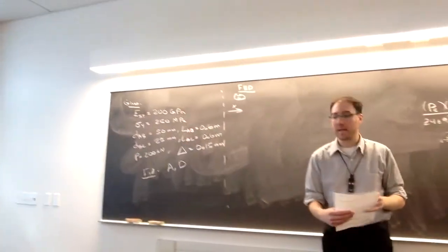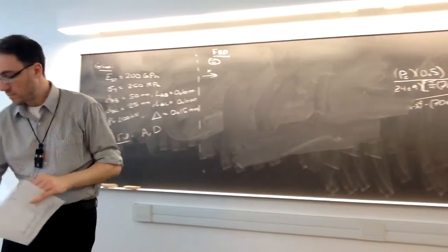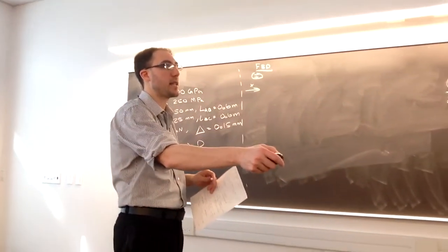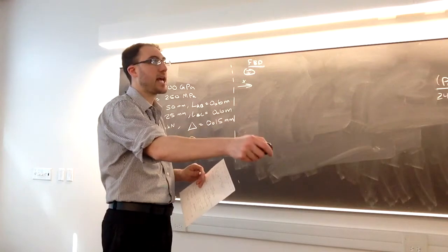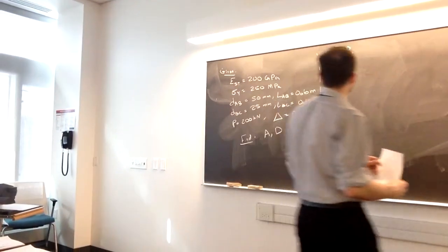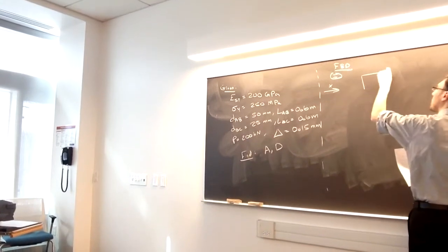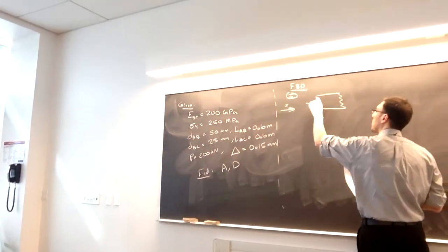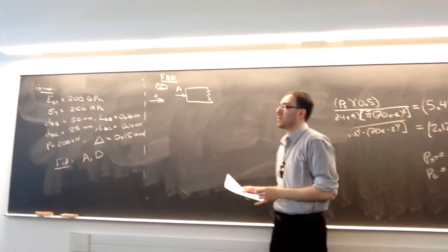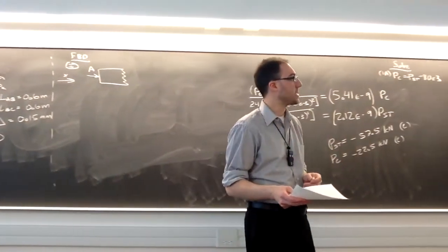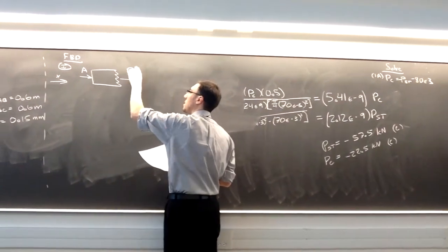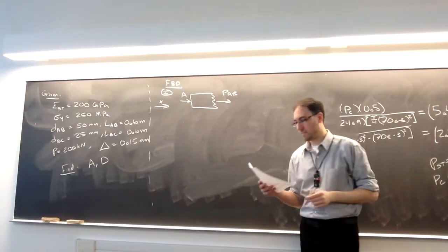First section, if I make a cut through this area here and take everything to the left-hand side, I'm keeping the wall reaction in this picture. So I have the wall reaction on the left-hand side, and where I cut through it, I will have the internal force in section AB.